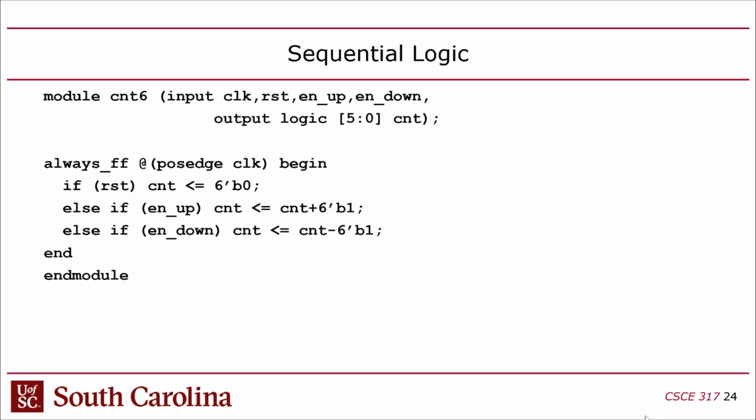Bus controllers, like an SPI master or slave interface, or a JTAG interface, are essentially all built with always statements. Now you could say, wait a second, you could bit bang it in software. It can, but it's kind of uncommon. They call that bit banging, if you ever see that term. Bit banging is when you have a GPIO pin that can be directly controlled by software, and then you write a program in C or even Python that manipulates that pin to implement a protocol.